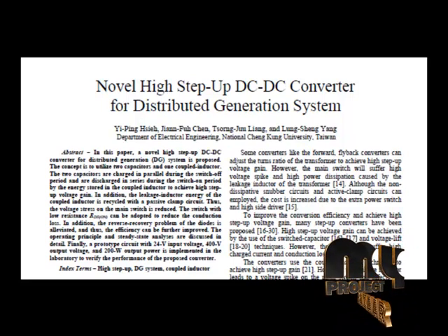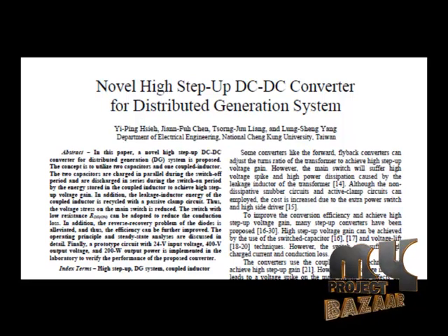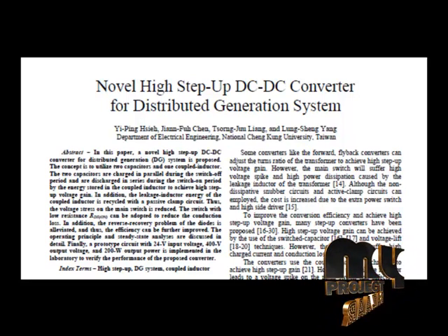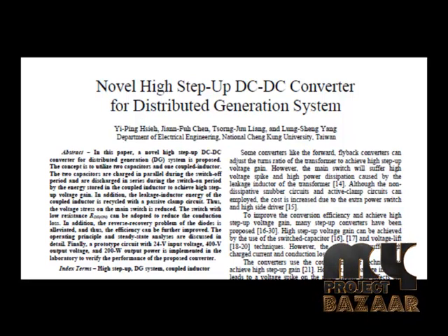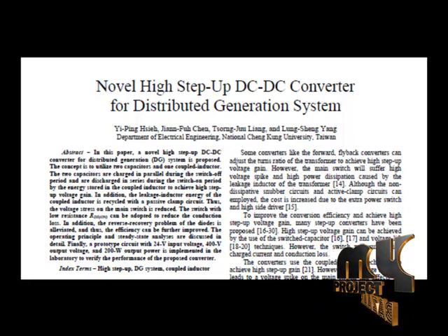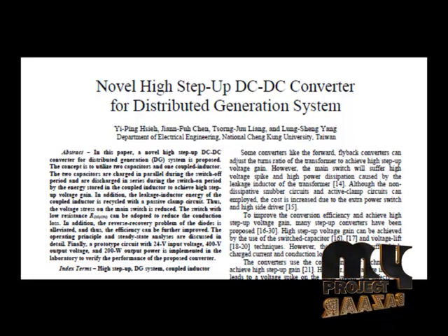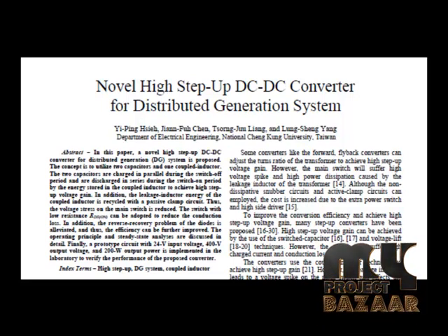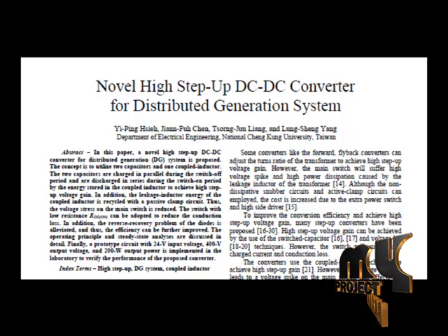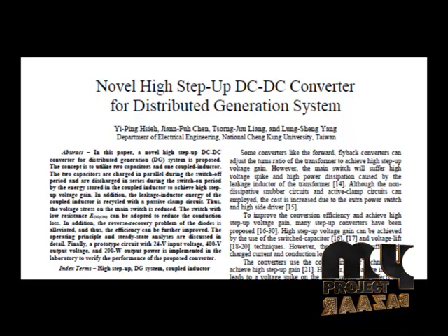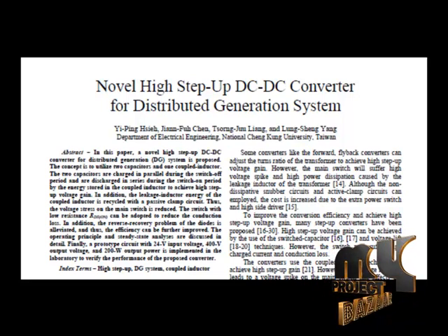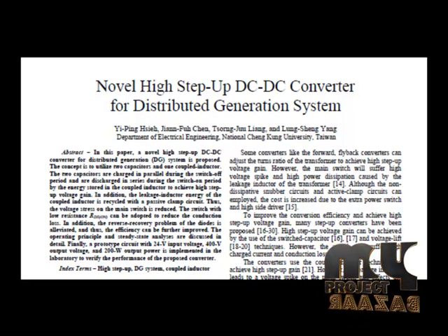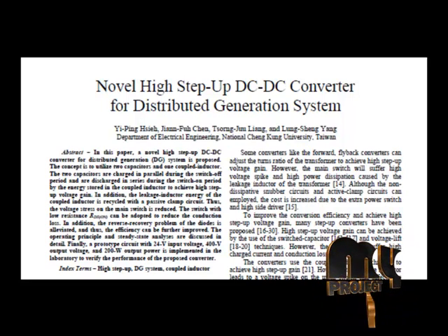The number of voltage domains within an integrated circuit is increasing to satisfy stringent power budgets. The increase in the number of voltage domains requires new techniques to generate this voltage close to the load circuitry while occupying a small area. Classically, power supplies occupy large on-chip area and are therefore not appropriate for point of load power delivery.